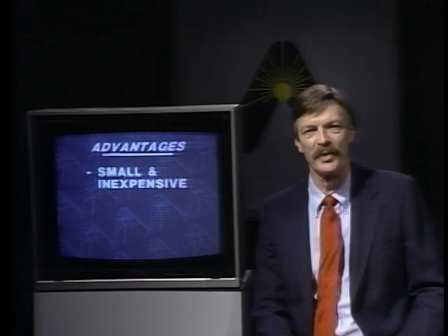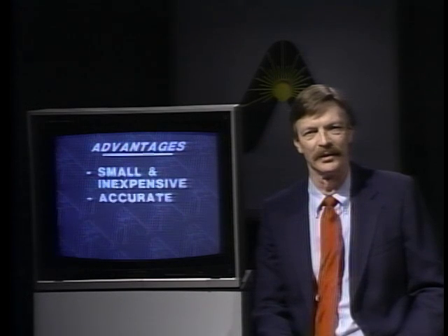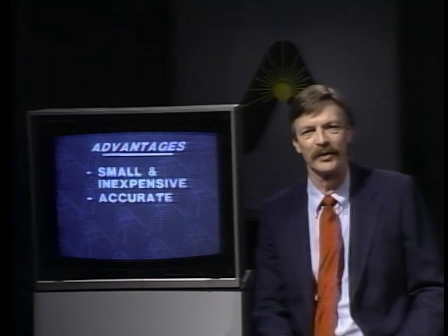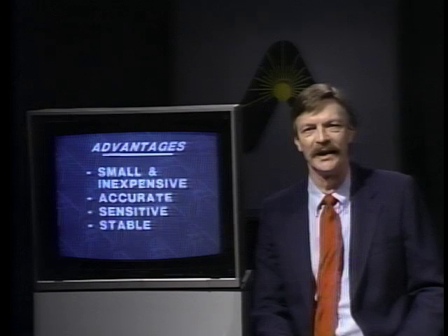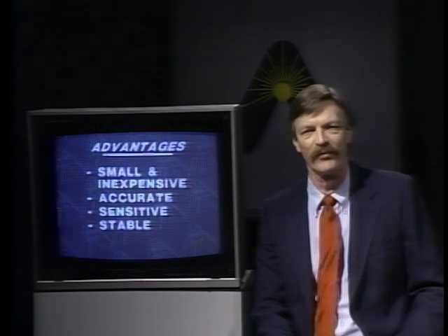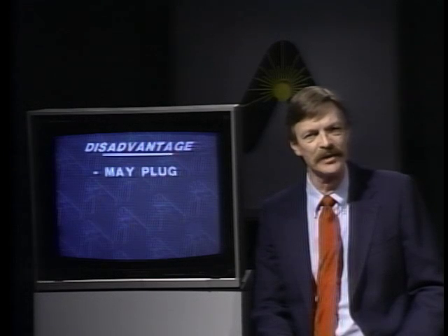The internal pilot piston-operated PRV has several advantages that make it a good choice for steam system service. It is comparatively small and inexpensive to purchase and install. It exhibits excellent accuracy and sensitivity, is highly stable at all flow rates, and has a long service life. The main disadvantage of internal pilot-operated valves is that the internal piping is small and may plug up with dirt.